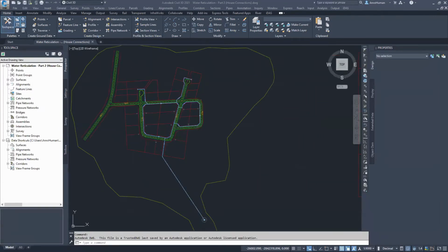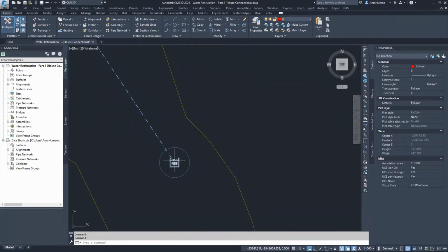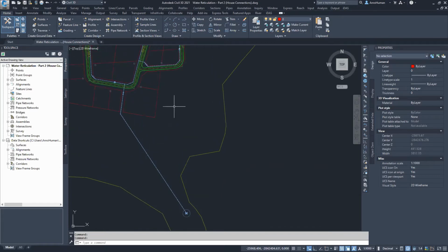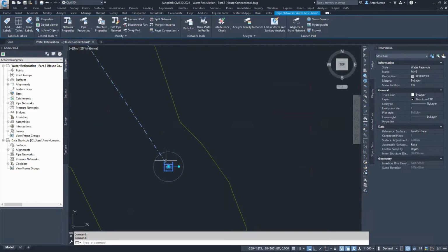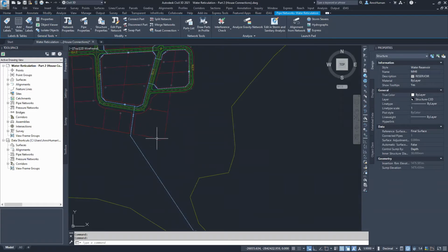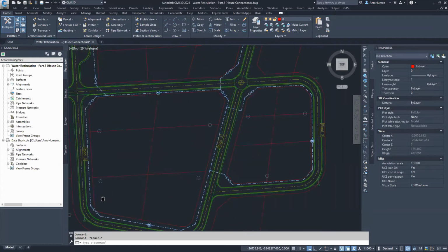All right, so what I've gone and done here is I've already changed this now to a reservoir. This was a tank with full bulk water, but as soon as we switch over to water reticulation, this needs to become a reservoir. A reservoir basically says that this point is now being fed constantly by a bulk water network. So it can be assumed that it has an infinite source, it's basically an infinite water source for the water reticulation.